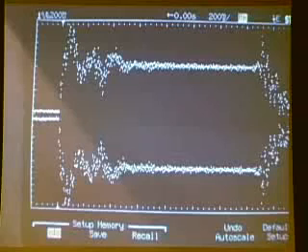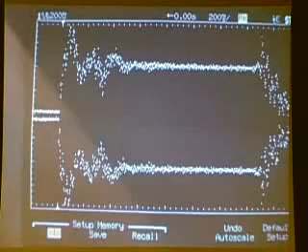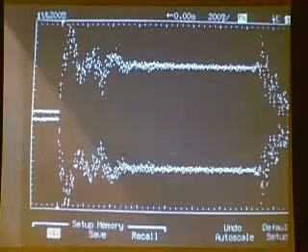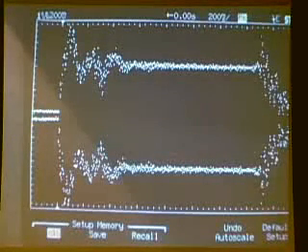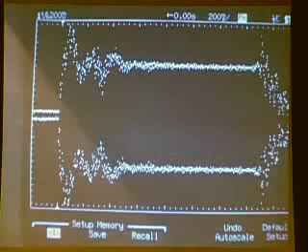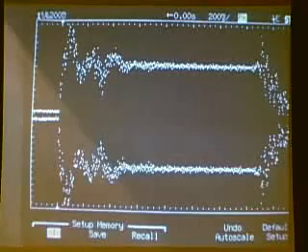We see a signal that is about 27 Hertz. We've measured it, it's very close to 27 Hertz. I therefore conclude that that must be the beat frequency between the 575 normal mode and the 548 Hertz normal mode. That difference is 27 Hertz. And you see that phenomenon, that beat phenomenon, obviously dies out. It is a transient.